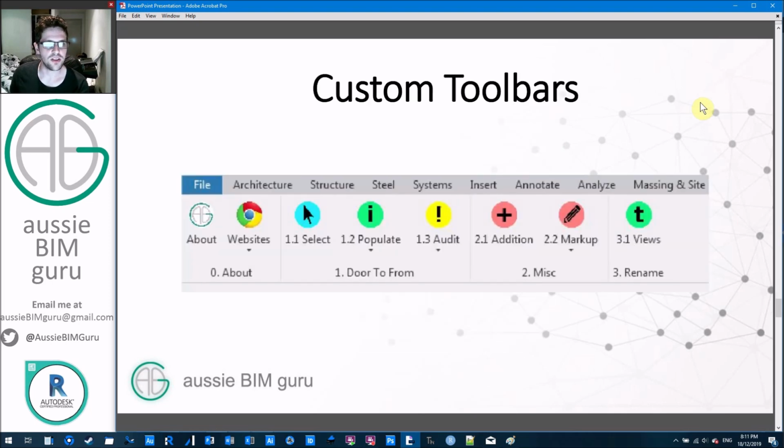But essentially, this is something that I built in about an hour, and each one of these buttons is a Dynamo script or a set of Dynamo scripts that can be deployed like a toolbar. So you can click on these buttons and it will execute a script. There's some different ways to collect your inputs, which I'll show you. So for example, collecting the active selection is a little bit more tricky than it would be in a standard Dynamo script where you do something like select model elements, but very efficient.